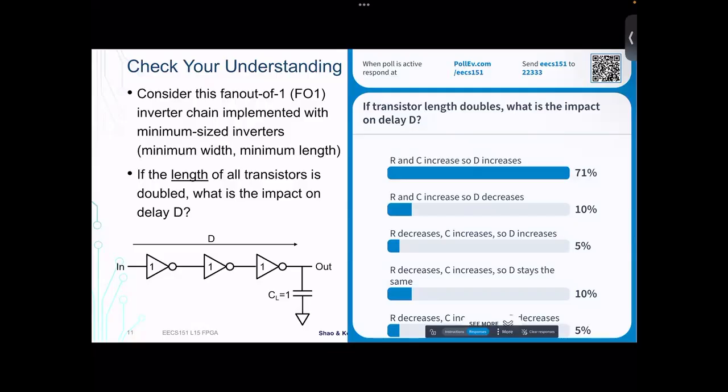Occasionally, we will build transistors that are minimum width and greater than minimum length, which makes them really slow and crummy. But it turns out that there are certain cases where we actually want slower delay. We haven't talked about those cases yet, but it'll come up later. So just keep in mind that length is also a sizing parameter in our transistor model.